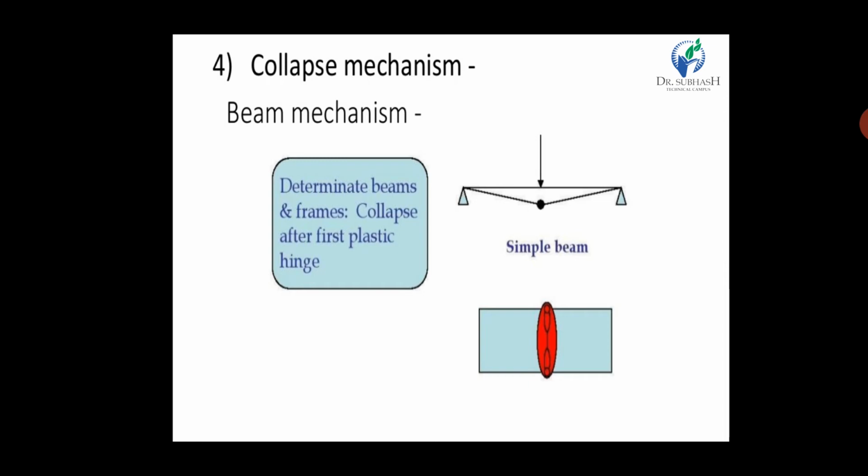Generally, hinges are located at the distant ends, at the interaction of members, and at the point of load. At a connection involving a change in geometry, we also provide the plastic hinge. And at the point of zero shear in a span loaded by UDL throughout the beam. So these are the places where a plastic hinge should occur.